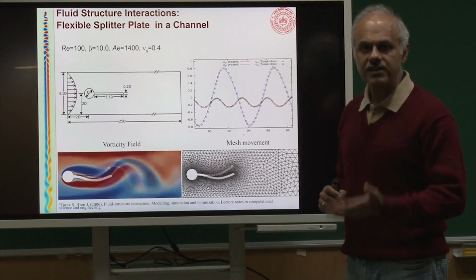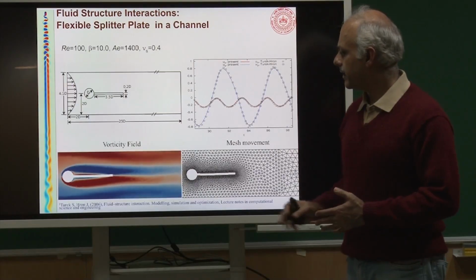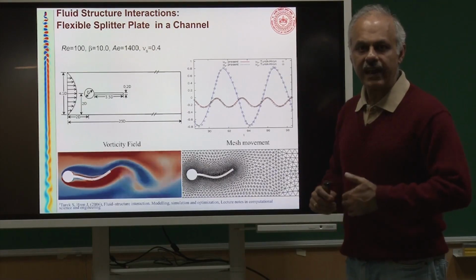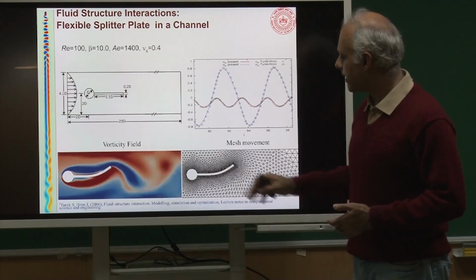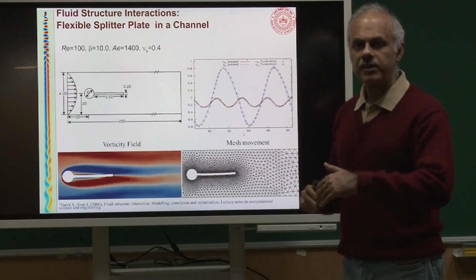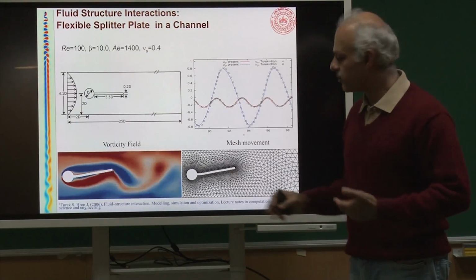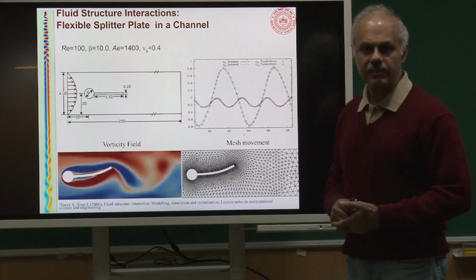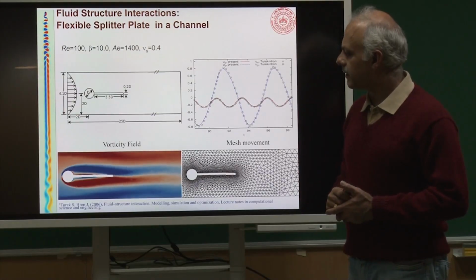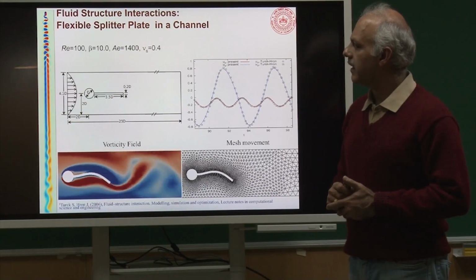We have to solve the equations for fluid mechanics, we have to solve the equations for solid mechanics, then there is a grid, and this gridding has to be done dynamically on the fly as the body deforms. The loads from the fluid have to be transferred to the structure, and likewise the deformation and the velocities that you get on the structure have to be transferred back to the fluid. Okay. So, we have done many other problems. This was just a test problem for fluid structure interaction.